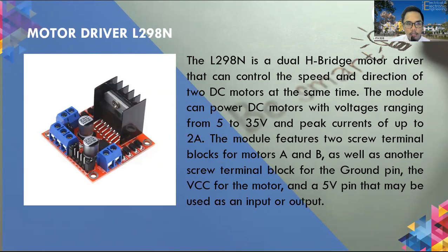Next is the motor driver L298N. The motor driver is a dual H-bridge motor driver that can control the speed and direction of two DC motors at the same time.